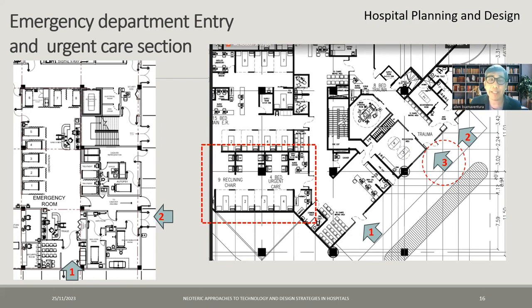The plan on the right is a 3-entry facility, with the third entrance for patients going to the emergency. The third entrance will take patients who are using medical ambulances as a transport vehicle. The patient inside the ambulance has already called the hospital emergency triage for priority care to the resuscitation bay or minor operating room. The area enclosed by the red box is the urgent care section for patients in code green, which is less urgent. Lazy boy chairs are provided for this type of patient.